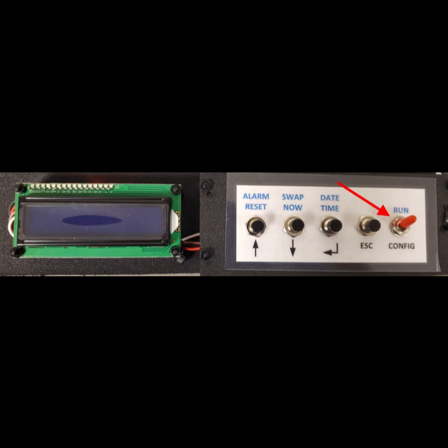Let's talk about navigating the configuration. The buttons above the up and down arrows scroll through the configuration menu. When you see a parameter that needs to be changed, press the Enter or left arrow button and that will take you to the edit screen for the parameter. The up and down arrows are used now to adjust the parameter value. Use the ESC button to go back to the configuration menu. When you are finished with the configuration, place the Run Config switch back to run.